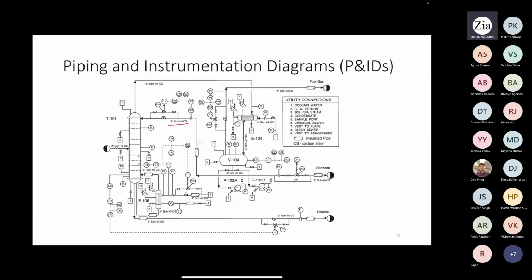You will have a pH meter, so the pH meter will just sense the pH, and based on its sensing, it will send the signal to the control unit. The control unit will judge the signal and check whether it is maintained at the set pH. If it is maintained, then it will not send any action. But if it is not maintained, suppose the reactor is to be maintained at neutral pH, but due to some reaction, the pH in that particular reactor is about 8. Now the control unit will compare the value with the set value. The set value is your desired pH, that is neutral pH.